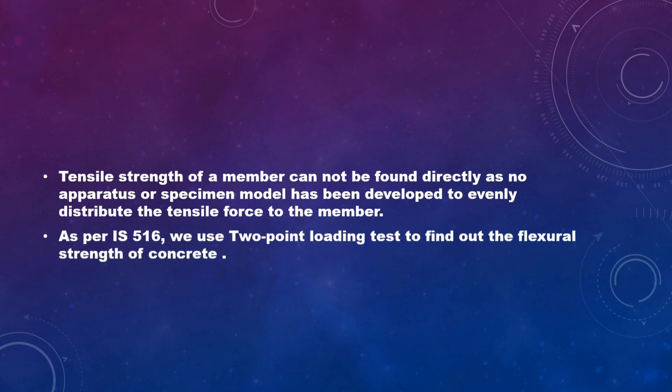As per IS 516, we use the 2-point loading test to find out the flexural strength of the concrete. The flexural strength measures the ability of the concrete to resist deformation under load, which is crucial in assessing the durability of the material or the structure.